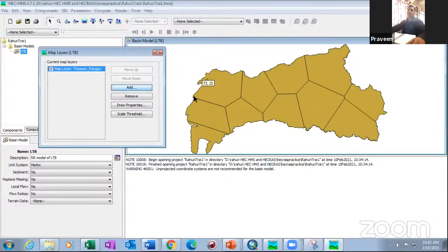Suppose you have a rain gauge here and you compute rainfall for the entire area from it, does that make any sense? No, right? Because the influence will hardly be within 5 to 10 kilometers radius. If it goes beyond that, there might not have been rainfall in this area, and you're unnecessarily giving rainfall there. So this non-rainy area will contribute unnecessary rainfall and runoff, and that will add error into your modeling.